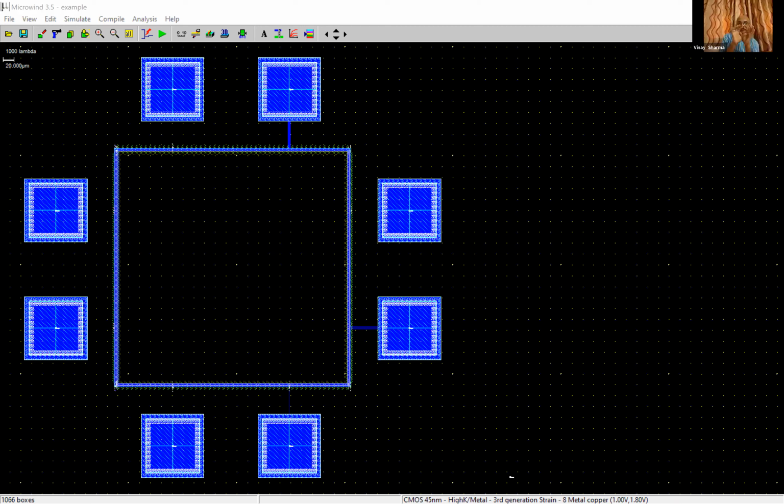That's not possible because you need to have pads which are significantly big in size. So we were trying to reduce it. I go to my data and go to pads and set one pad in X, in Y, and the ring width, I try 0.5, something 10 times smaller. So this small size probably.